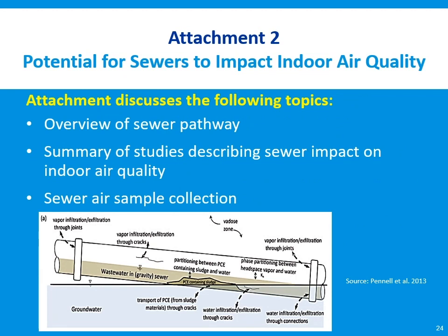Attachment 2 in the supplemental guidance addresses sewers and their impact on indoor air quality. The attachment provides an overview of the sewer pathway and provides guidance on how to collect samples of sewer air. Recent studies have shown that organic vapors can move significant distances due to sewers. The transport of vapor due to sewers is not associated with the engineered backfill material that surrounds the sewer, but rather vapor transport occurs within the sewer pipe itself.